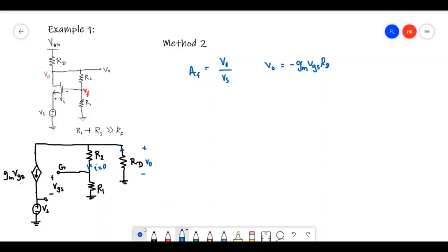So using this, now let's try to find Vs, right? So the voltage here is actually Vf, so we can find Vf. So Vf is, taking this network, R1 over R1 plus R2, voltage divider, right? So R1 over R1 plus R2 into V out,